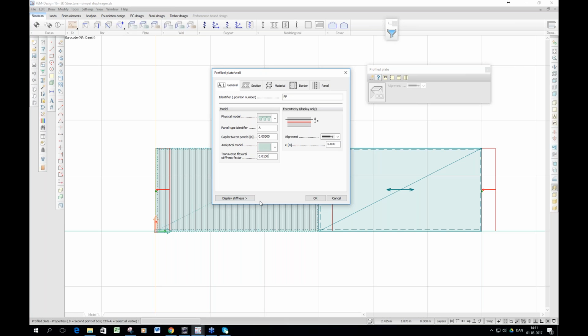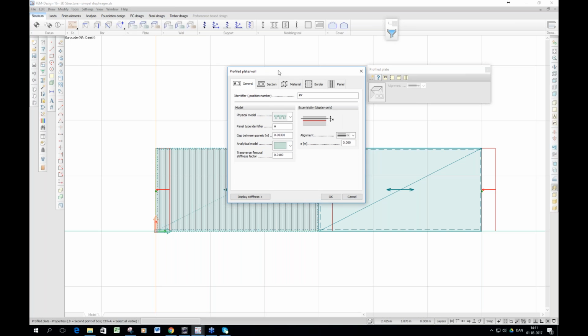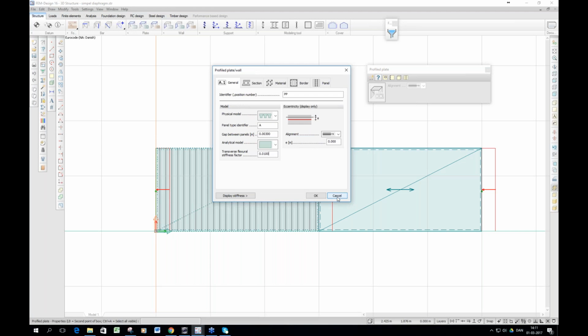That in-plane shear stiffness, if we apply the diaphragm upon it, will be infinite anyway. So then we have solved this small problem. Of course, if you have large buildings with deep plates, the effect is smaller. If you have small, thin buildings, the effect of the diaphragm is much bigger. So it depends on the geometry where you can really gain from the diaphragm function.